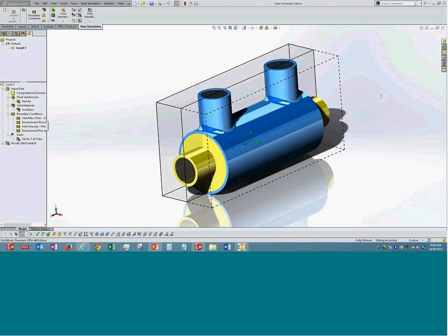There is something called initial mesh over here. Right click on the input and go to initial mesh. One part was what we did here automatically. Another option is that I don't want automatic settings.